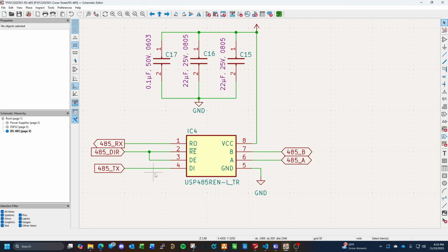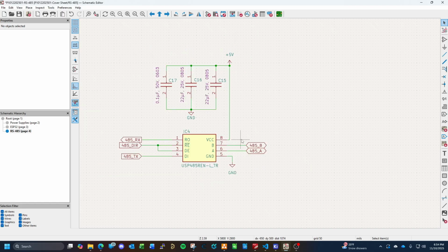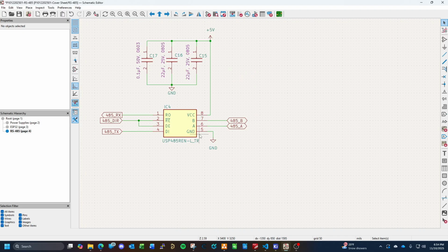It reaches out, says, "Hey, I'm looking for a device with this address." All devices will pick it up. They'll read in the data. The bus will have the exact same signal. All devices will read in the same data. The device says, "Hey, I'm that address," and it'll send out its response, and the microcontroller is going to be listening to just that device. So that's how we're going to set it up and how it's going to be programmed.